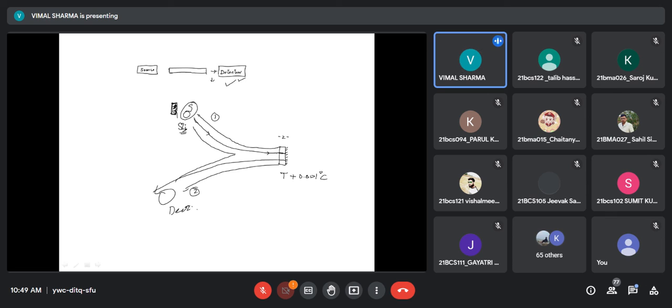But if there is a slight change in the temperature, even this much, then the silicon will absorb a different amount of light. Due to this change in temperature, it will absorb more or less light, and that change in intensity of light is detected by the detector. So there is modulation in the signal detected by the detector, and this modulation happens due to the different amounts of light absorbed at different temperatures at the silicon.